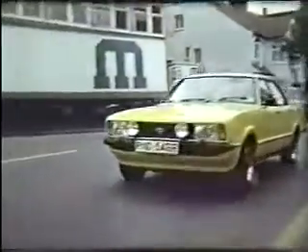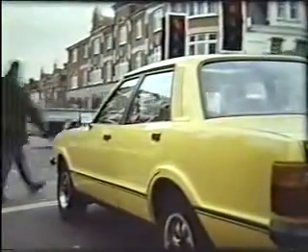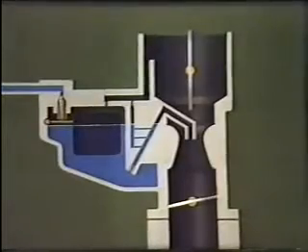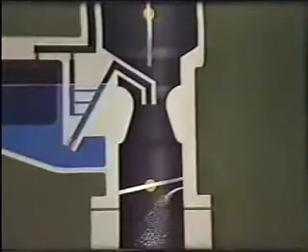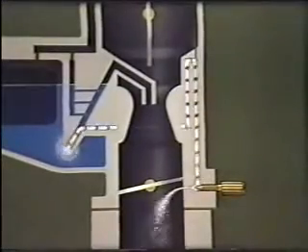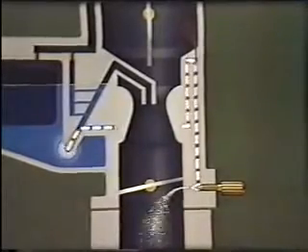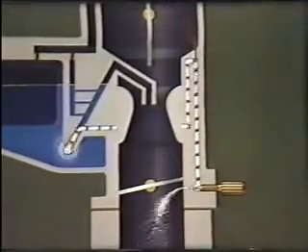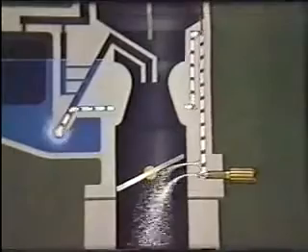At normal idling speed, the airflow is not strong enough to pull sufficient fuel into the venturi to keep the engine running. To do this, a small amount of petrol is injected into the side of the throttle nearest the engine. This is the idling jet. Petrol is delivered from the float chamber, air is drawn from the upper part of the venturi, and sufficient mixture is provided for the engine to idle. In normal acceleration, a progression jet provides more petrol until the main jet takes over.